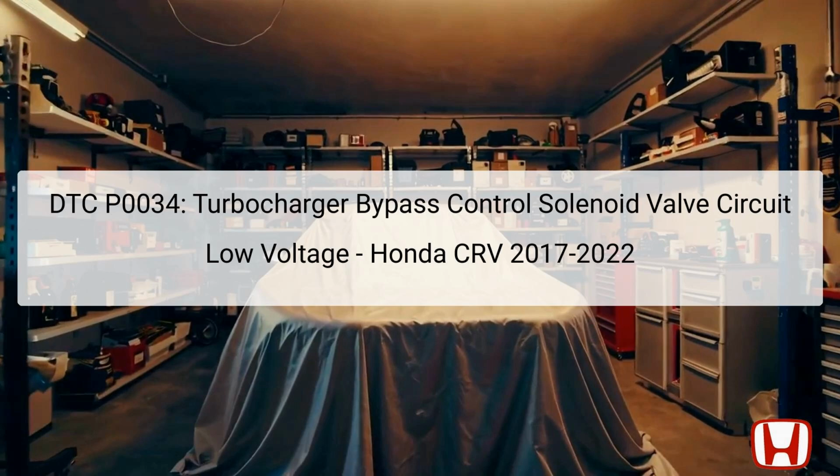The low voltage condition may indicate an issue with the solenoid itself, or associated wiring components such as connectors and fuses. This diagnostic trouble code, DTC, is significant because it can impact engine performance and efficiency, leading to potential drivability issues. It's crucial to follow the troubleshooting steps outlined to effectively diagnose and resolve this issue, ensuring the turbocharger operates as intended.